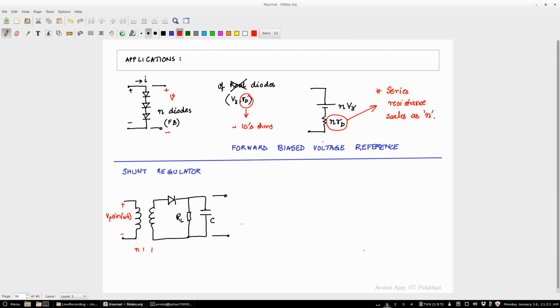Okay, what is the value of the peak that develops in a half rectifier? What is it related to? If I assume that this is an n:1 transformer, and I call this V sin omega t, then what is this DC value roughly? The voltage across the capacitor is Vp by n. All the ripple and everything comes over this, but the DC value is roughly Vp by n.